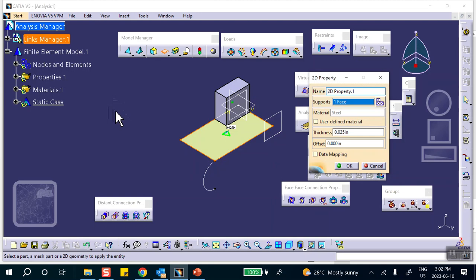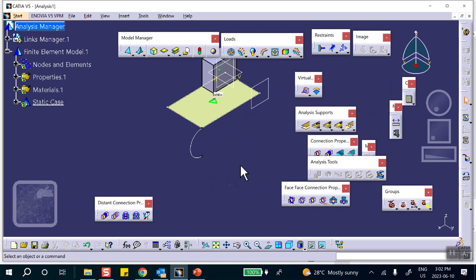Now remember, there is an inherent inconsistency in the way I'm doing these problems, assuming these thicknesses are so small that it doesn't matter whether that block actually sits on the middle surface or on the top, etc. So for real life, you have to worry about these things. Good. Now we're going to mesh this guy.